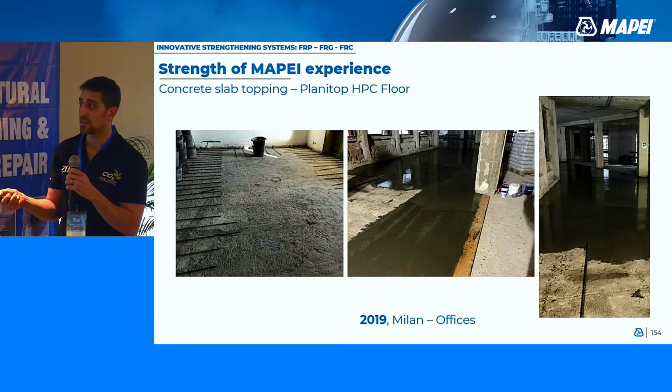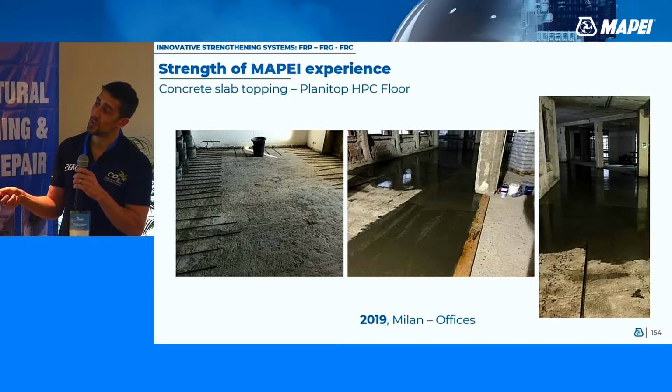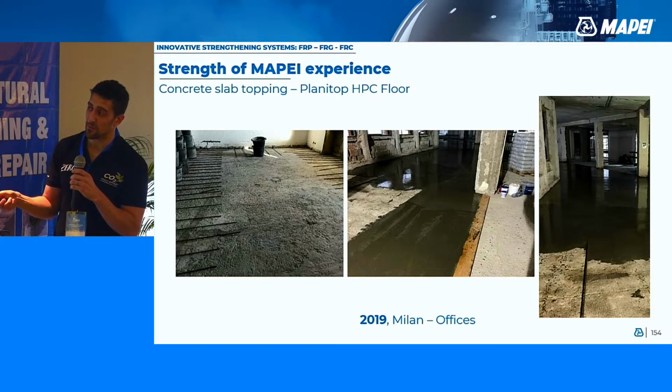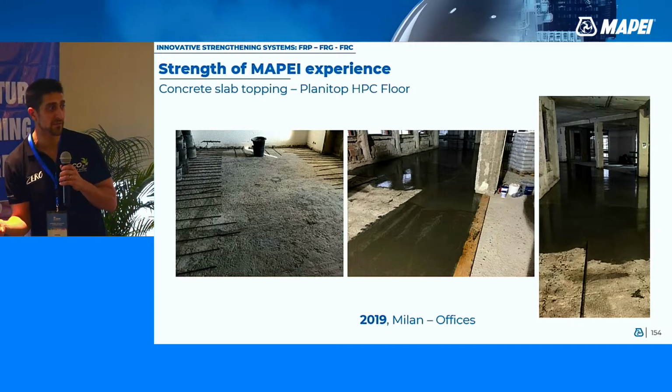This concrete topping, okay, in this case was a seismic retrofitting. So you can see that we have placed steel rebars along all the perimeter in order to let the transfer of load between the concrete topping and the beams and the surrounding element of the slab.